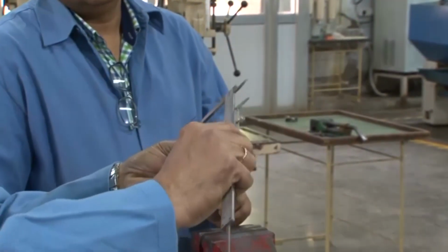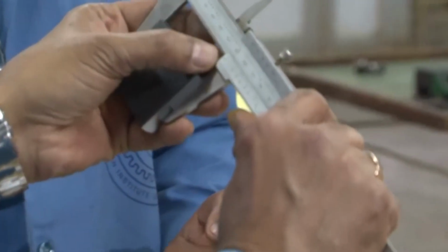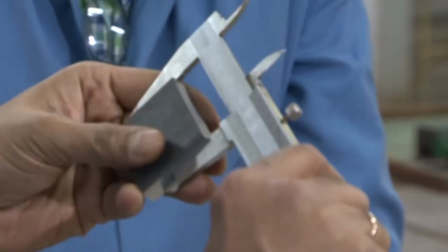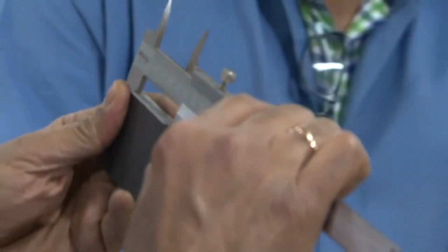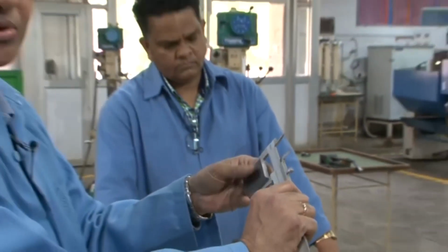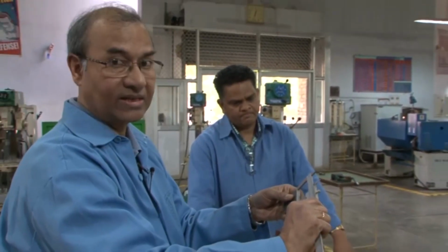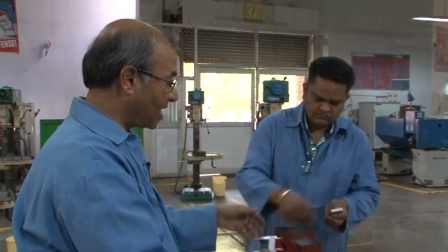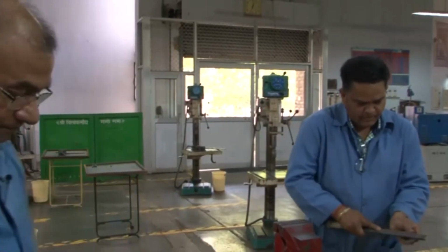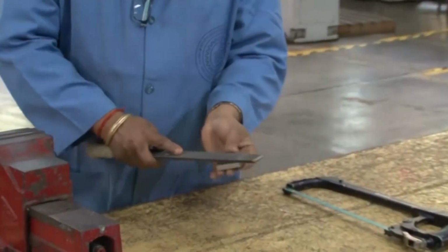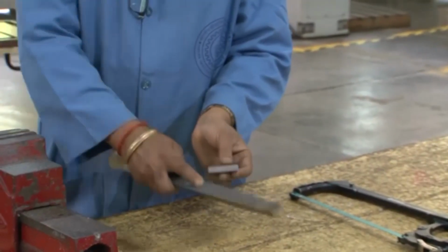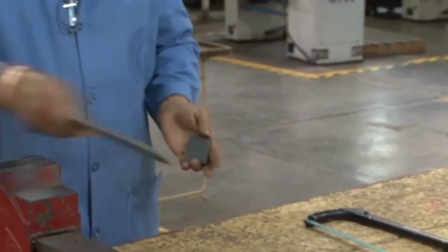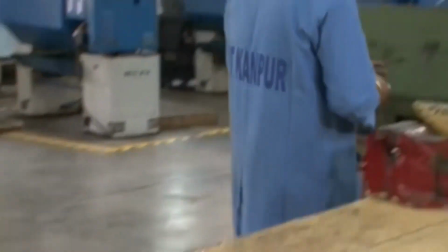Of course, the vernier caliper is there. So, you can quickly check by reading the main scale and the vernier scale, and where the two scale readings are meeting, you multiply by the least count, which is here 0.02, and so on. This has been already told to you in the PowerPoint presentation of the metrology session, and then we have to mark for making the hole. This is to remove the burrs, because when the filing has been made, there are some small burrs appearing. So, now it is perfect, and we stop.